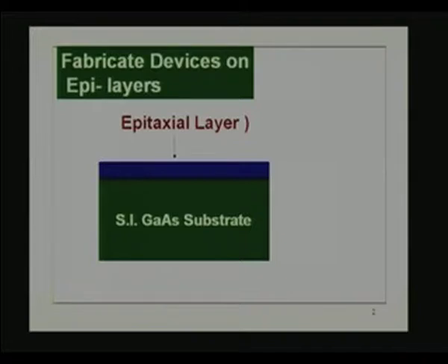layers on the top of the semi insulating substrate. So, that is the epitaxial layer, which ultimately we said will be the one which will be used for making the devices. Now, when you want to make these devices in integrated circuit, what you need is not merely the ability to make device, you must be able to isolate the devices from one another in integrated circuits. For example, in the case of silicon integrated circuit, very popular technique is p-n junction isolation, but when you want high performance, there also you go for semi insulating substrates.